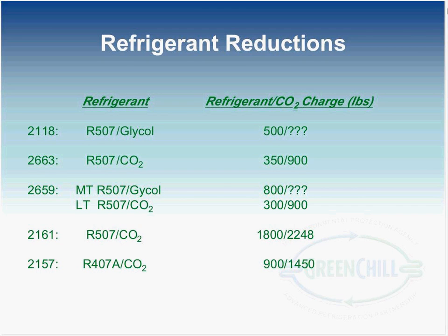We do not track our glycol capacity, so that's why the question marks in those 2 store columns there. But as you can see, the primary refrigerant is relatively low, as is the secondary, except for the 2 Cascade systems, which, when you consider that the CO2 is used in both the medium temp and low temp cases throughout the store, is a relatively small charge.